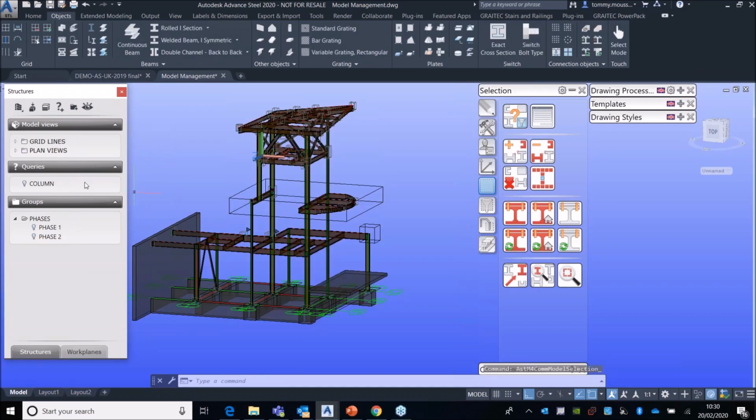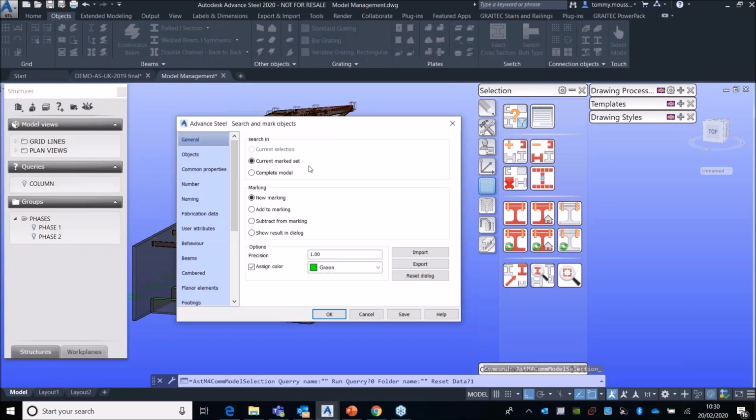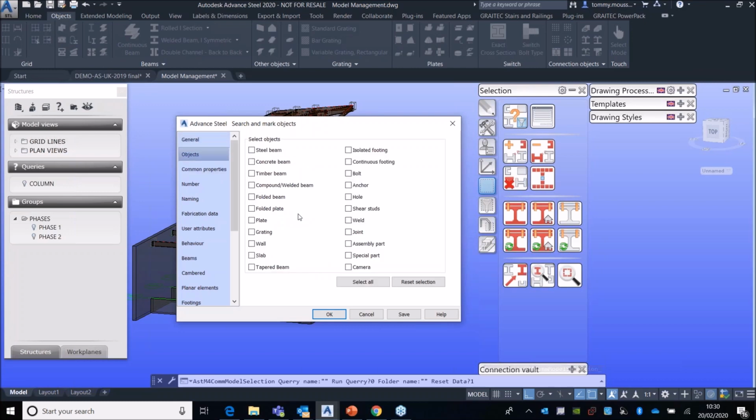That being said, if I were to go here to queries and create a new query, it'll remove all the previous settings. Okay, that's why I prefer to always go to the search filter and create a new query afterwards, because it would have been much easier just to select a new model role as opposed to having to check multiple boxes here. Of course, my query was quite simple, but if you have a granular search created based off of phase and material types within that phase, things of that type, it can be annoying to have to redo all that work.